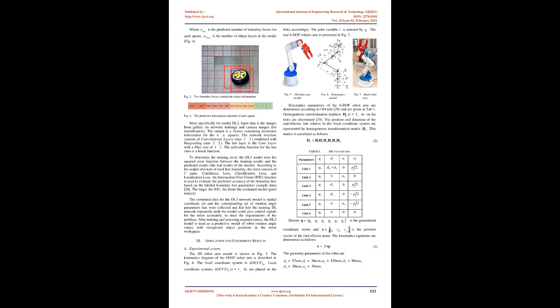Object recognition based on computer vision technique with DL2 model. After the system recognizes the voice command, the robot arm begins to move in the workspace. At the same time, the camera performs the continuous imaging task to detect and recognize the required object according to the output information of the ML model. When an object is recognized, information about the position of the object is converted to a control signal that moves the gripper to the position of the object to perform a programmed action.